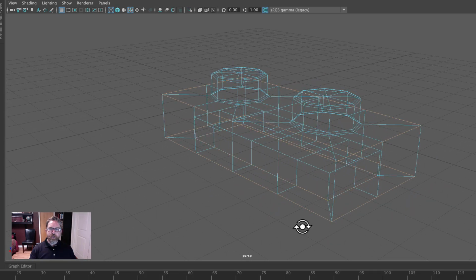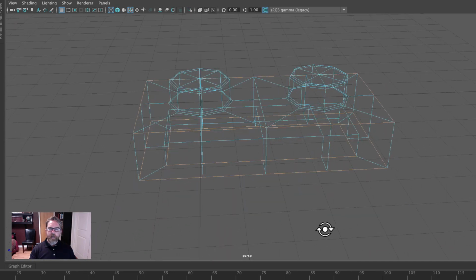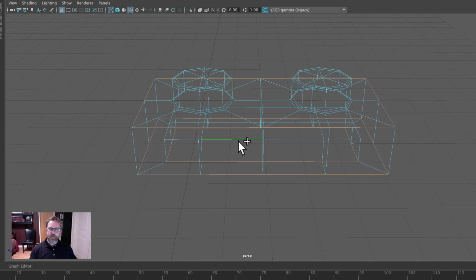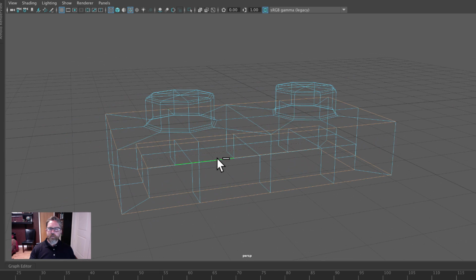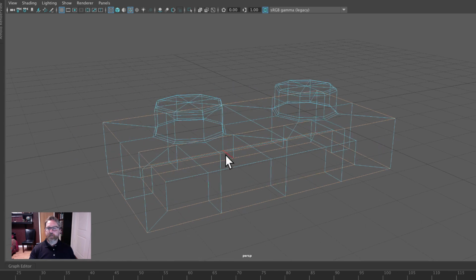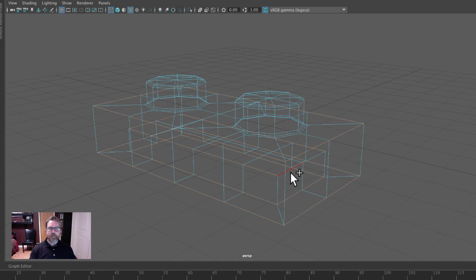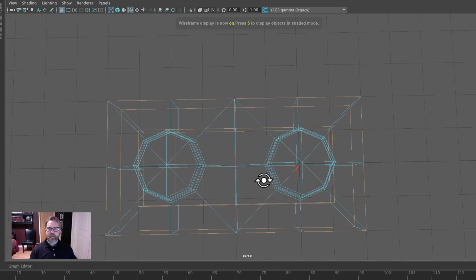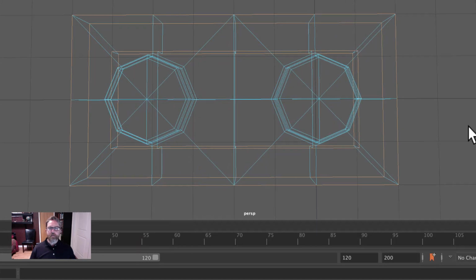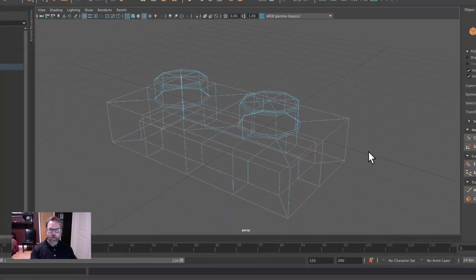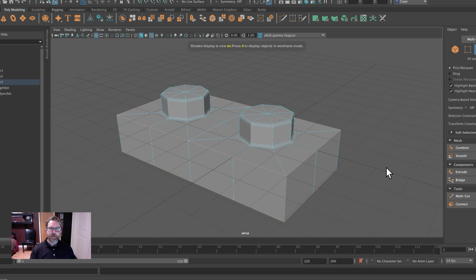We'll shift double click the interior bottom, and then in this view in the wireframe, I can shift double click. That gives me 1, shift double click 2, shift double click, and I got the wrong one there. Shift double click and shift double click. So once again, I've got the 4, in this case, rectangles. You can see those 4 rectangle selections there, rectangular edge loops. And now we'll select the corners, maybe easier in the 5 mode.